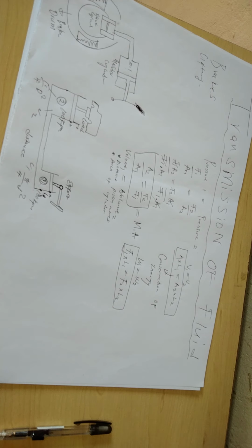I will make a drawing and explain my statement. It converts hydraulic power input at a low pressure into a reduced volume output at a higher pressure. Why do we need them? We need them so that we can get a high pressure in the system.